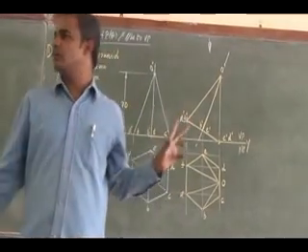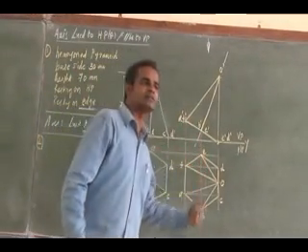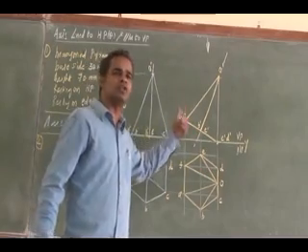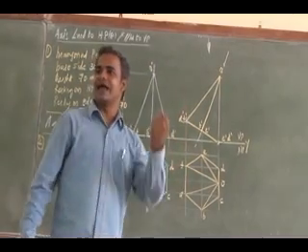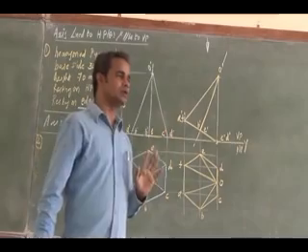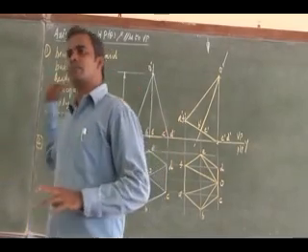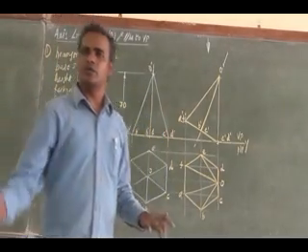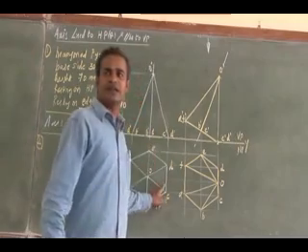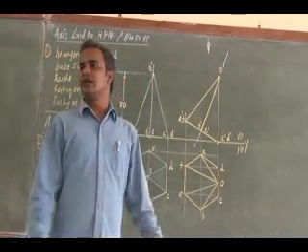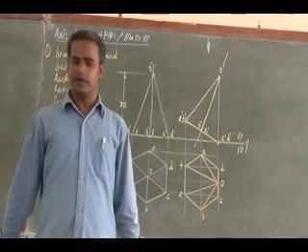The problem is a different problem, right? Either a triangular slant face is perpendicular to both HP and VP, or a slant edge is vertical. So two problems are possible. Is it clear? Instead of a triangular slant face, a slant edge can be given.